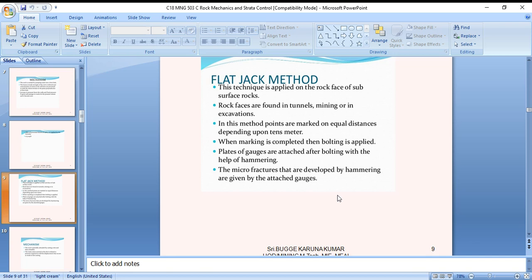However, if this pillar is cut from the mine roof, the pillar strain will be reduced to zero, and the gauge will indicate the absolute increase in the strain. Furthermore, this measured strain has the opposite sign of the absolute strain that existed in the pillar before it was cut.